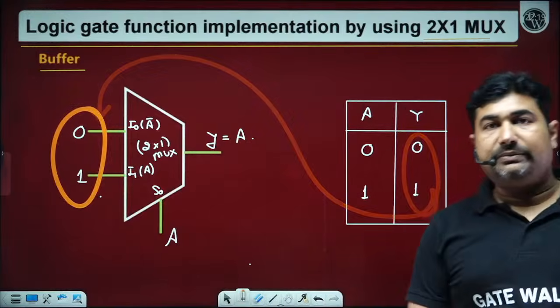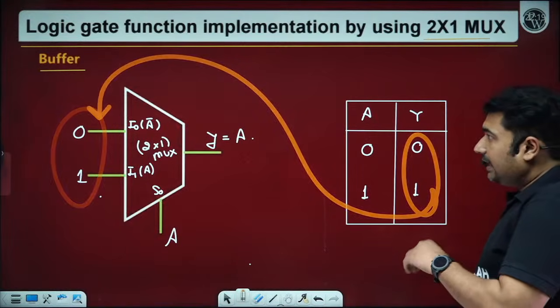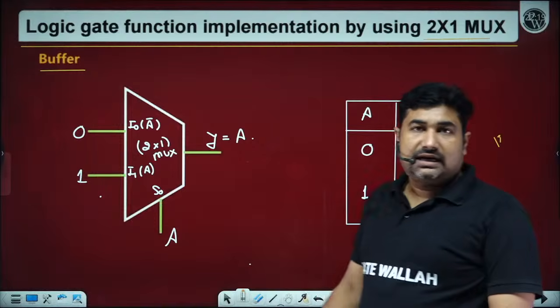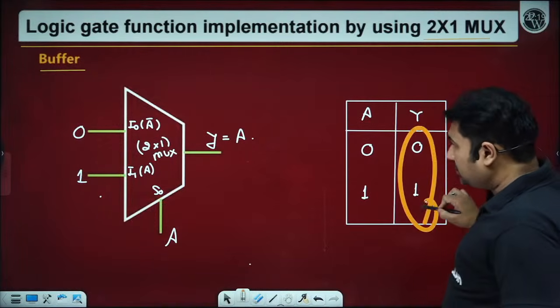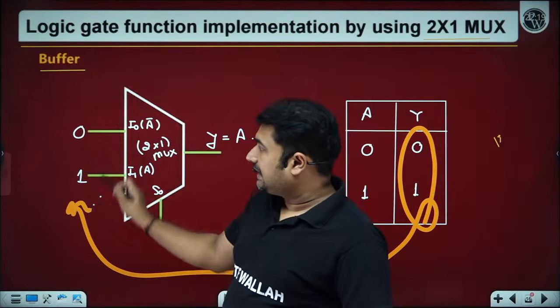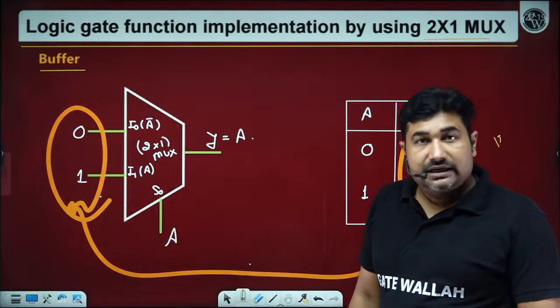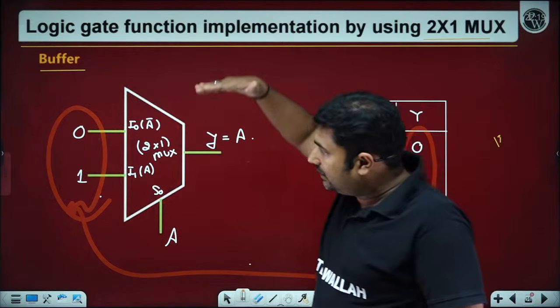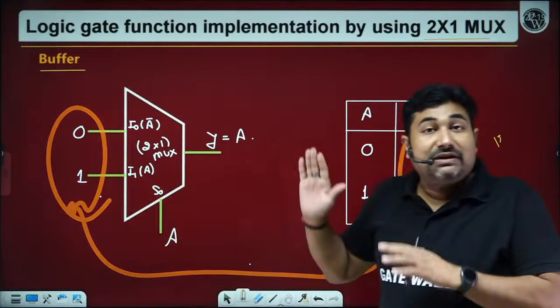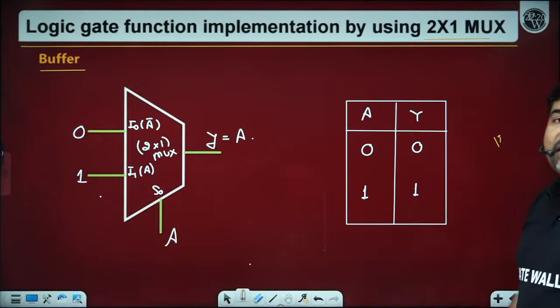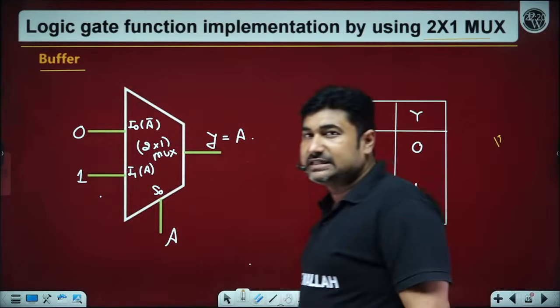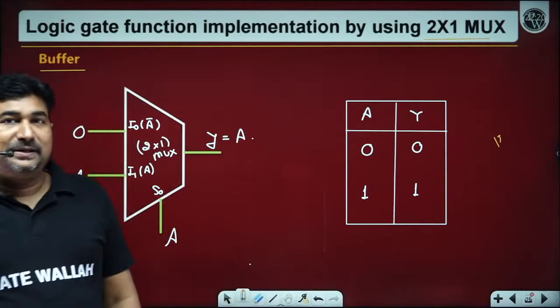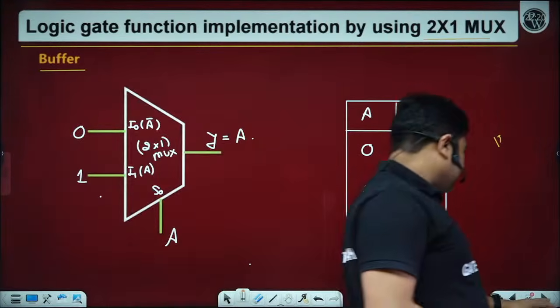How many of you are able to understand? In case all the variables are onto the select line, just copy the output of the truth table to the input of the multiplexer. Keeping one thing in mind, top to bottom is LSB to MSB for a standard representation. Otherwise, we have to focus on the representation as well. Easy? Let's talk about the NOT gate as well.